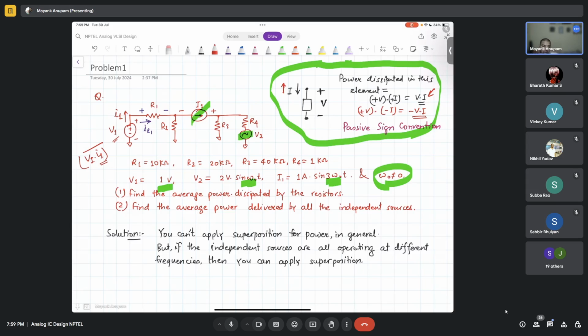But in another scenario you may calculate the power and it comes out to be 1 watt dissipation in the voltage source. That can also happen; there is absolutely nothing stopping it. In that case, if you have the same question, what is the power delivered by the voltage source, you will not say 1 watt or 0, you will say it is minus 1 watt, because now the power is being dissipated by the voltage source, not delivered by it. Are you getting what I am trying to say, Nikhil?